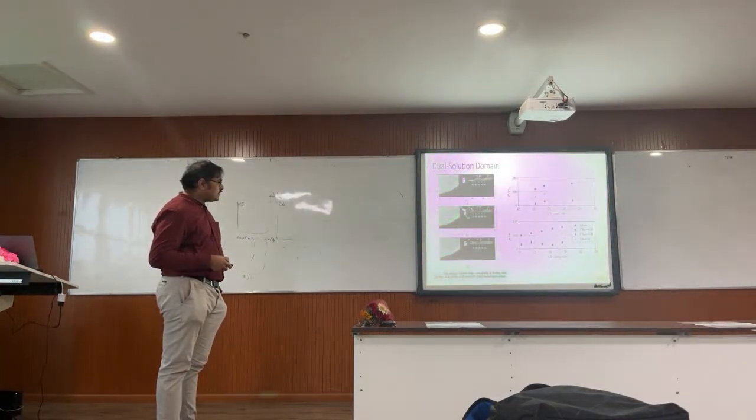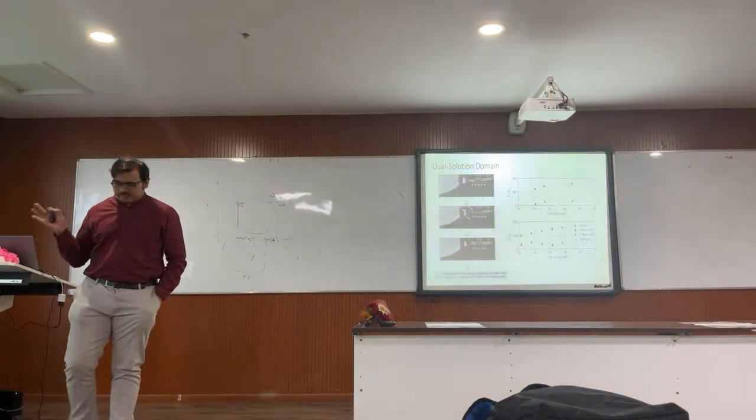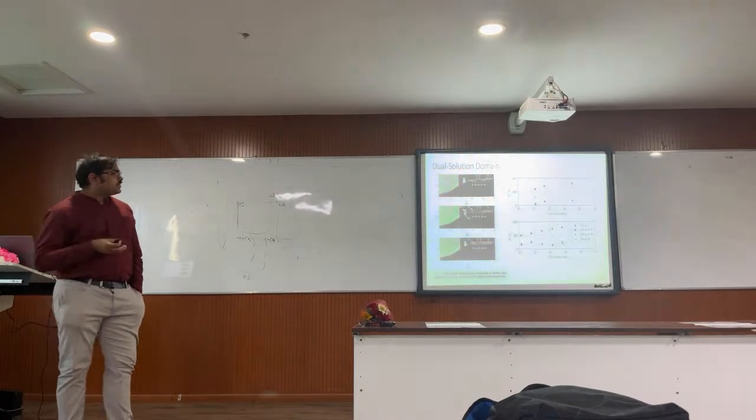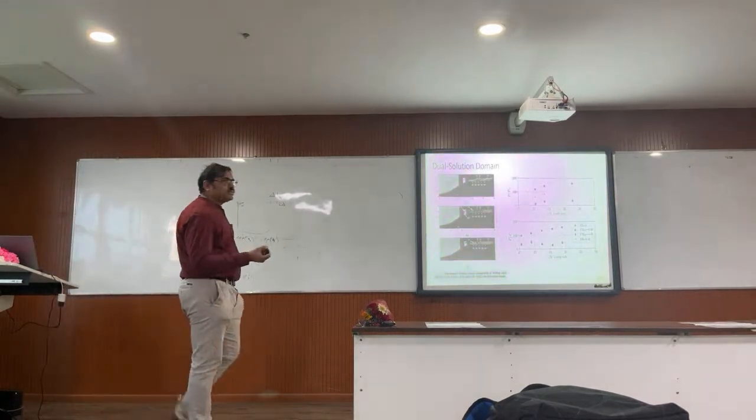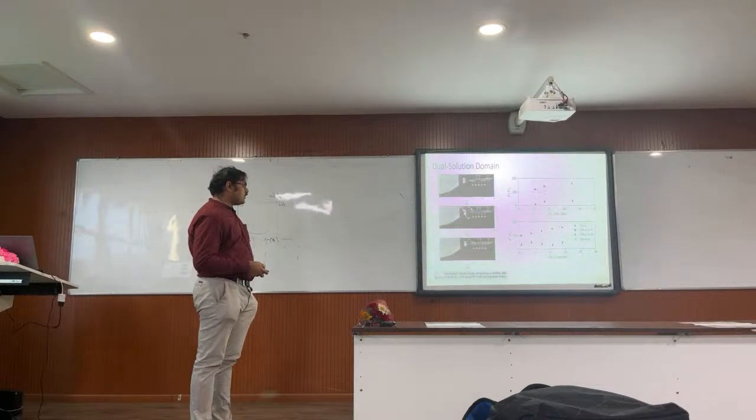if we started off, this is throttling ratio DF. DF is dynamic flap. That is case A here. Dynamic flap implies that initially you started off the flow and it produced a supersonic flow, and then you started moving the flap from behind. When the flap was moved to this throttling ratio of 0.35, it remained started. So it basically remained started, following whatever we earlier plotted for throttling ratio 0. The same plots were there.